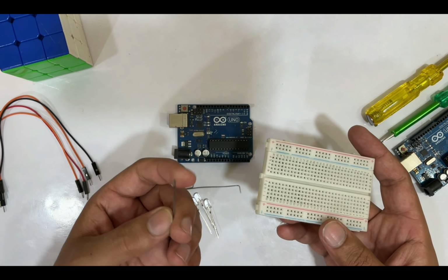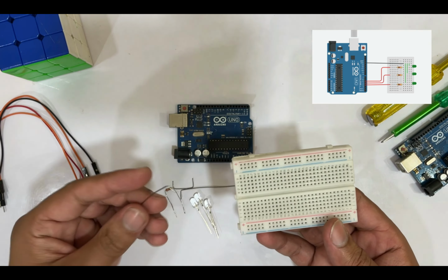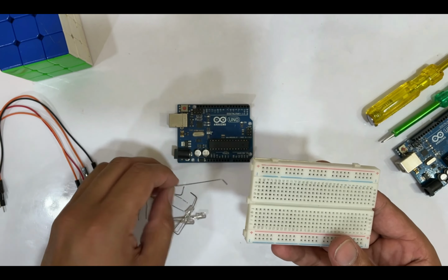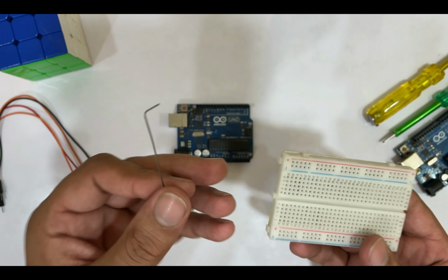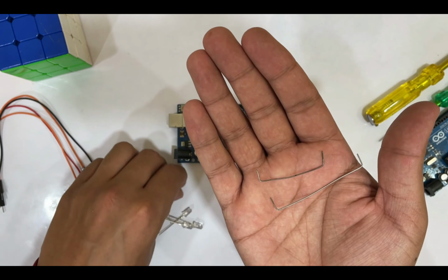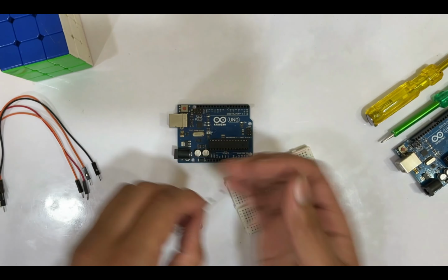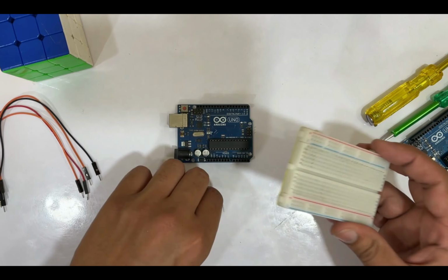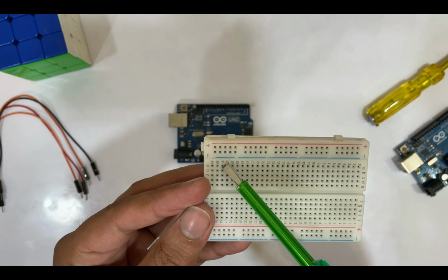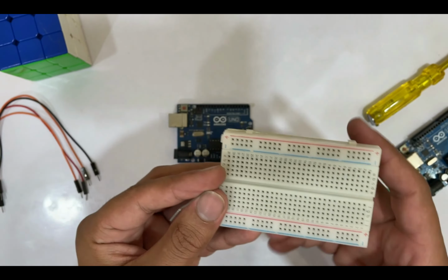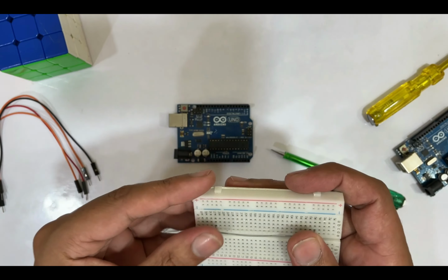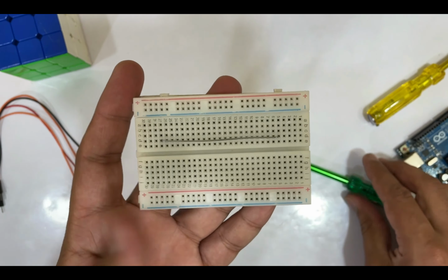So for that, we will first use these connecting wires to make the vertical lines common and make a common ground line. You can see here, these are just metallic wires which I have cut in different sizes. And it's not necessary that you must use these. You can directly connect the components. I just use them to make the circuits look cleaner. Now here I will use this line as a common ground line. So I will just insert one end here and the other on a different vertical lane, just simply like this one.